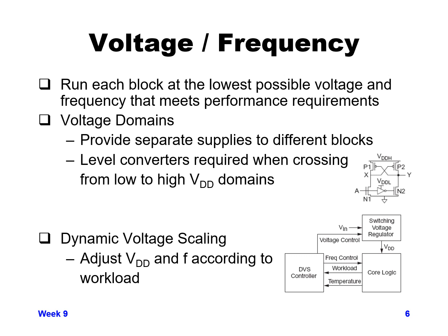And so when you do that, you want to make sure any signals coming from that domain have some sort of default as they're going into a domain that has power. If you're coming in from a domain that doesn't have power, you can run into problems, and so you have to have something that detects that and says default to a 1 or default to a 0 when the power domain that this signal is coming from gets turned off. So there's level converters and there's isolation devices to do that.